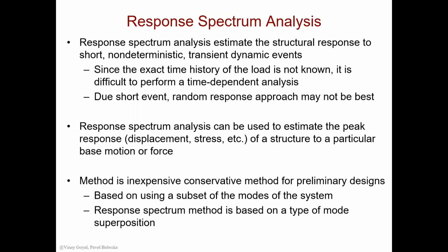Response spectrum analysis estimates the structural response to short, non-deterministic transient dynamic events. Since the exact time history of the load is not known, it is difficult to perform a time-dependent analysis. Due to the short duration of the event, a random response approach may not be the best approach here.